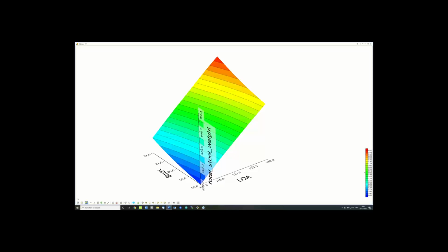I have used these results to set up a response surface model, which allows the accurate prediction of total weight and net present value for any variant within this design space. I will use this model to explore with you two of the most promising regions in this design space to find the optimum main dimensions of the vessel. And secondly, I would like to take this opportunity and show how a fully parametric model of a double-ended ferry may be set up within our soon-to-be released version, CAESES 5.